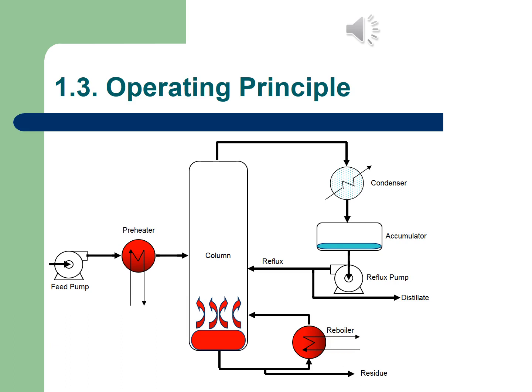Some vapor is going to start to form, and it will go through the condenser and be accumulated in the accumulator. As the process goes on, more vapor is produced, and in the accumulator, of course, you will have a larger top product. More feed is added to the column, so eventually you can see that your accumulator level is increasing. So again, larger vapor condensation takes place, and then you get the separation of the different components.